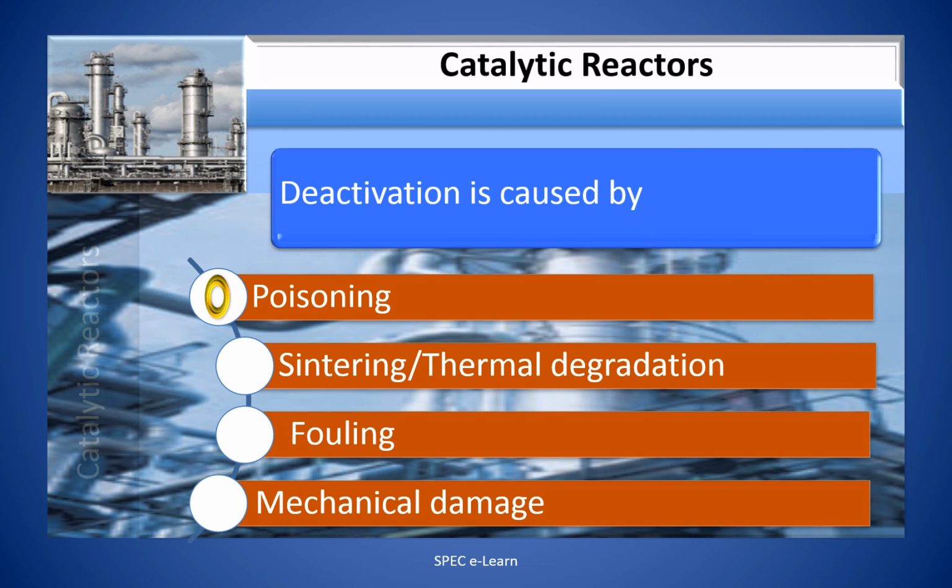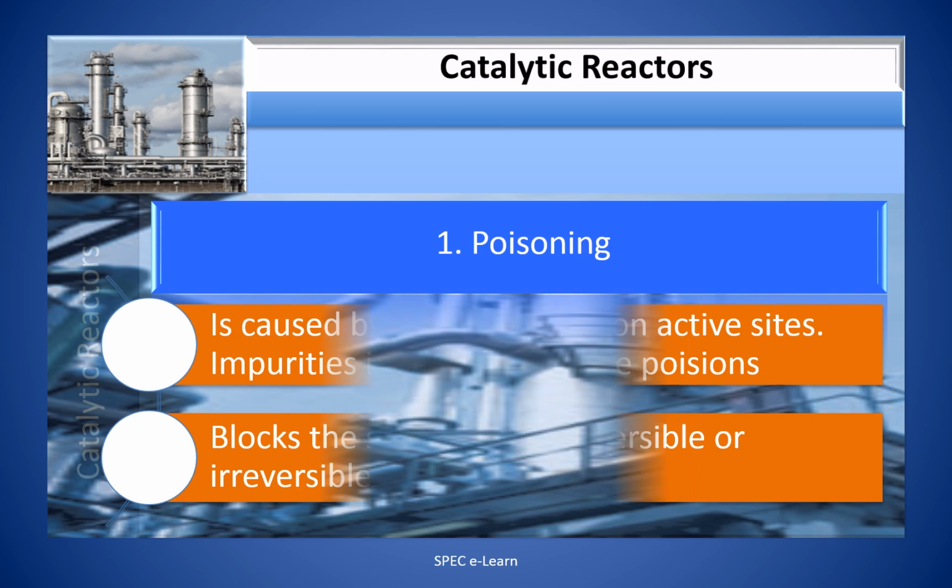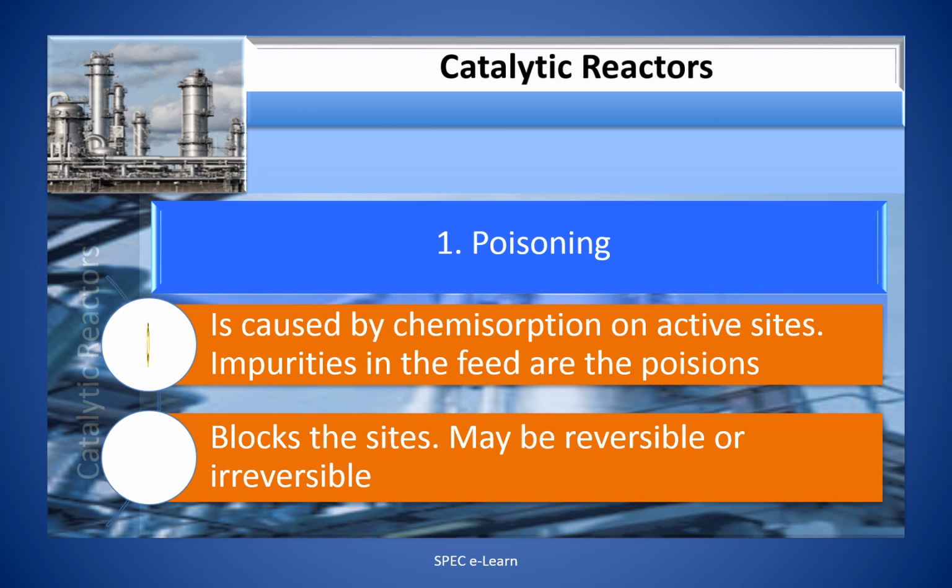Deactivation is caused by poisoning, sintering or thermal degradation, fouling, and mechanical damage. Poisoning. Poisoning is caused by chemisorption on active sites, impurities in the feed or the poisons. Poisoning blocks the sites, and may be reversible or irreversible.